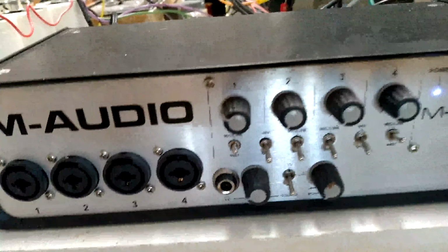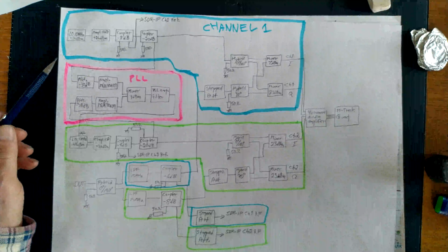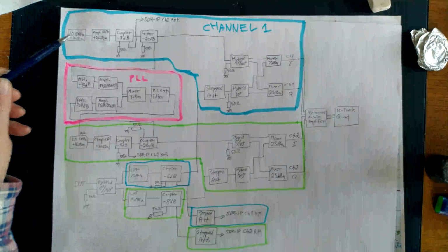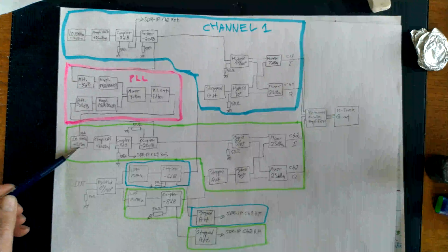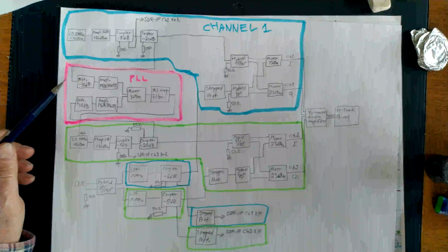Here is the schematic diagram. The heart of the system is two good 10 MHz oscillators, one here and one here. They are phase locked, but with a very low time constant. So they don't share sideband noise at frequencies above something like 0.1 Hertz.